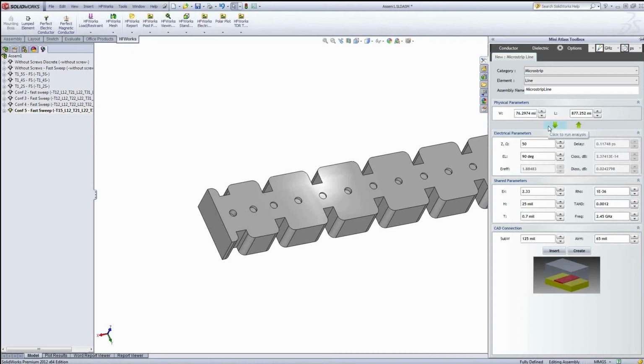This tool is basically a transmission line calculator. Oftentimes for electrical engineers, we need to draw dimensions based on electric properties. Let's say I wanted to make a printed circuit line, so I would probably want a 50 ohm line that's 90 degrees long, quarter wavelength at 2.545 gigahertz.